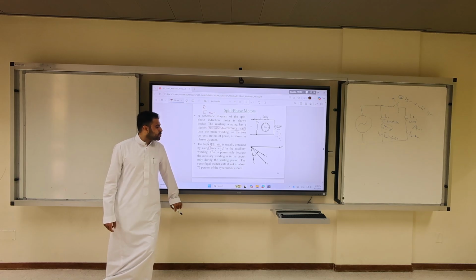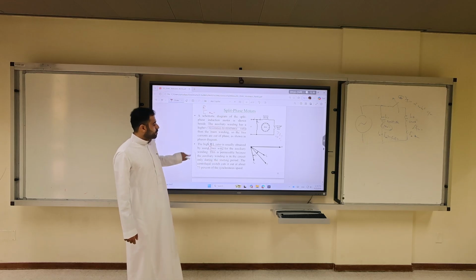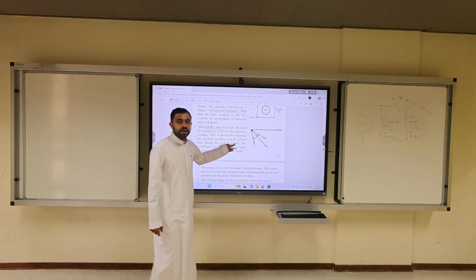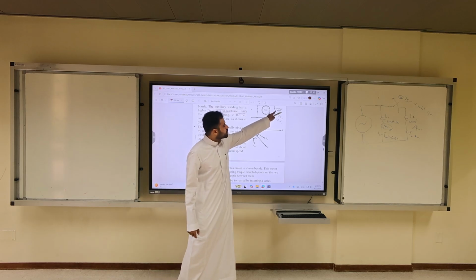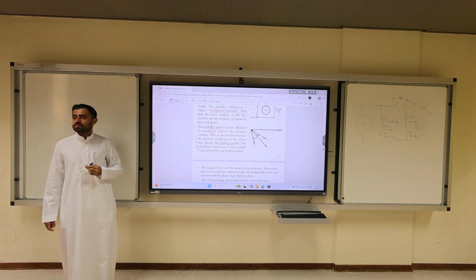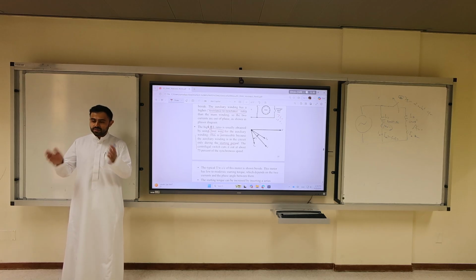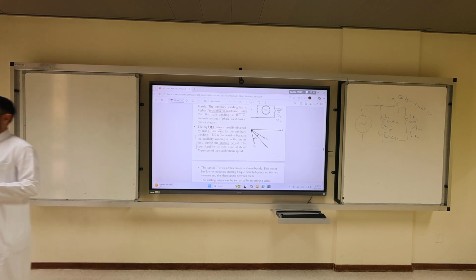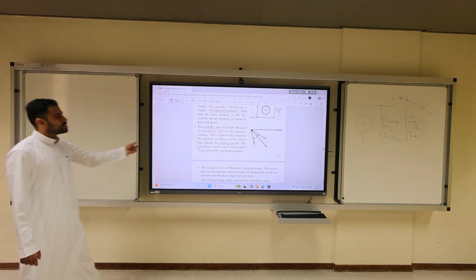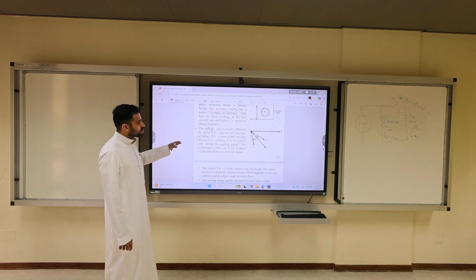You also want to make sure the auxiliary winding is in the circuit only during the start. Then we have an auxiliary switch. We close it at 75%. But what is the problem with the auxiliary switch? Mechanical problem. What is a usual mechanical problem? If we don't use power electronics, what will happen? The switch may jam. So this is the problem. That's why it's old school.